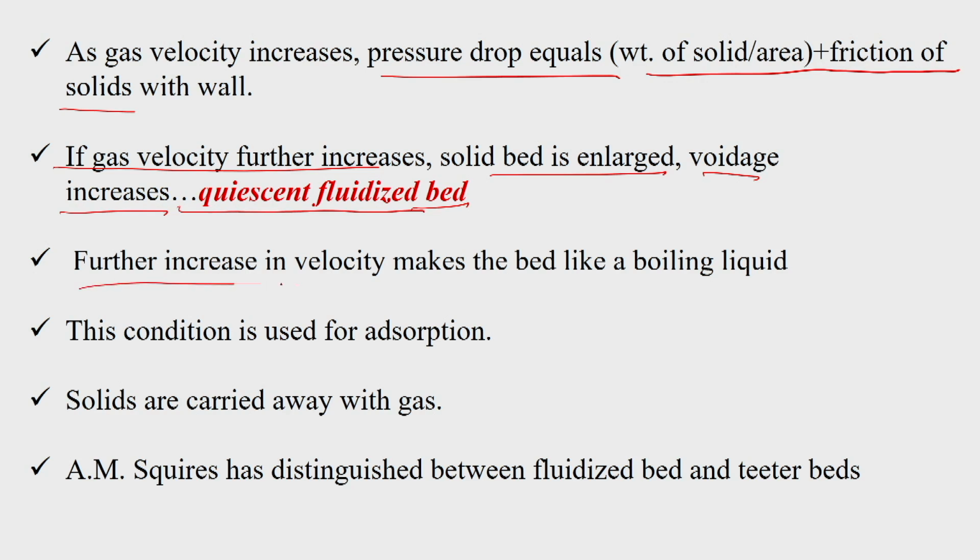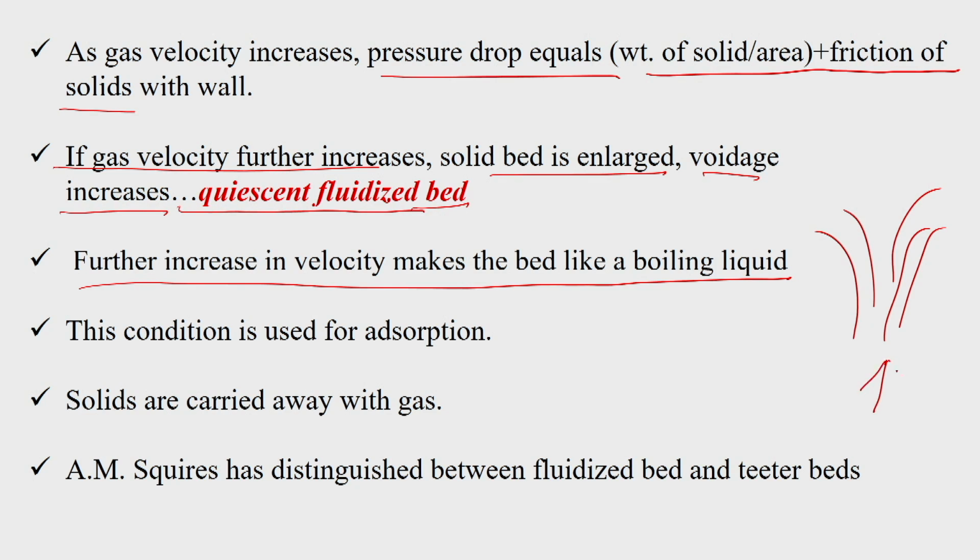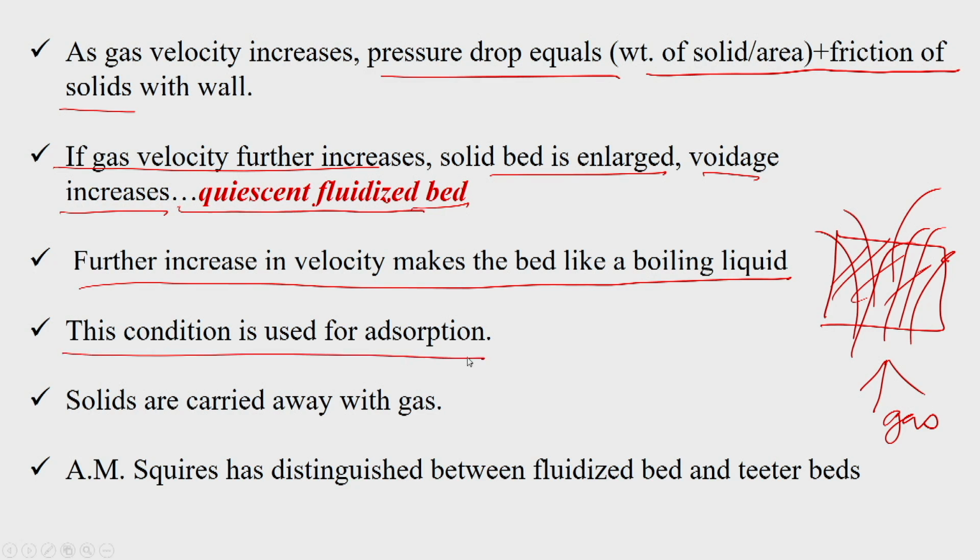Further increase in the velocity makes the bed like a boiling liquid. So, the entire thing will be boiling, like the solids will be boiling, because we are applying the gas from the bottom, and the solids are placed here, and they will be boiling like this. So, this condition is used for adsorption, and in this case the adsorption will be maximum. So, solids are carried away with the gas.